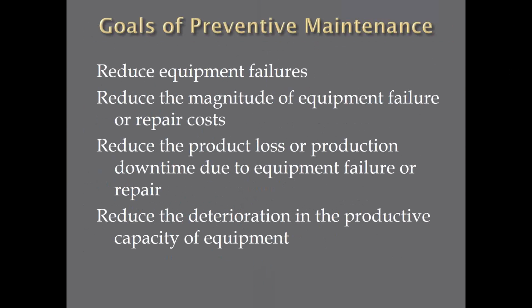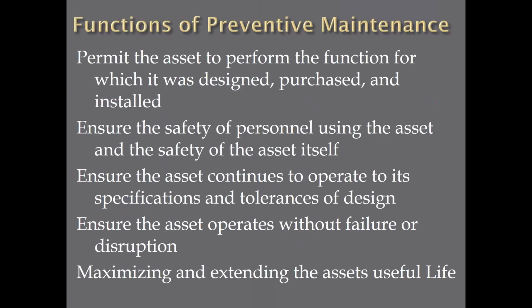Goals of preventive maintenance. Another thing for your maintenance people: reduce equipment failures. If your PM's not doing that, it may not be effective. What about reducing the magnitude of equipment failure or the repair cost? What if we reduce the product loss or production downtime due to the equipment failure or repair? Reduce the deterioration in the productive capacity of the equipment. All things that are effective with a good PM program.